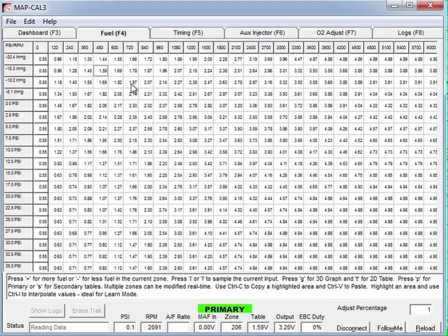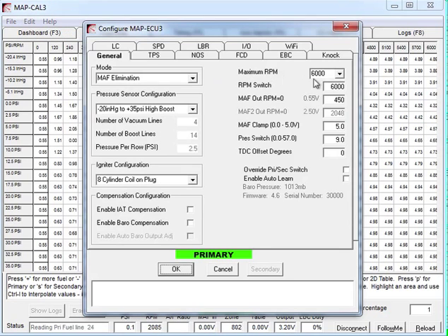The other thing you can do is position yourself on a cursor or a box or a zone and sample an input, like the TPS we showed you before, using the I key. Now this will sample the current MAF input if it's configured. At the moment you'll notice it went to 0, so that's because the MAF input is not configured. So I'll go into ECU configuration.